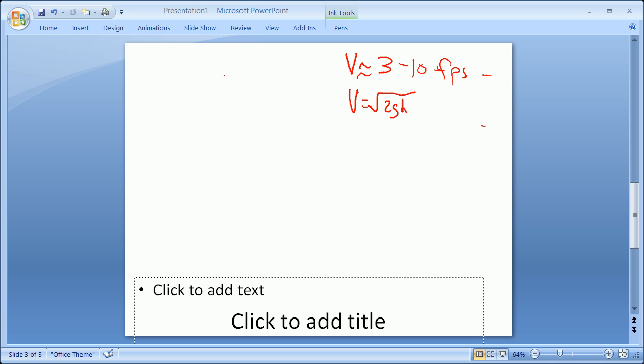Water systems often run at about 60 psi. And 14.7 psi is 33.9 feet of water, so you can start thinking about water towers 100 feet tall and all that. So that said, how does a reservoir system happen when it's not pumped? Water flows, once again, down pressure. You have a reservoir, you have a pipe, and you have free discharge.